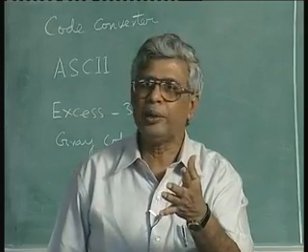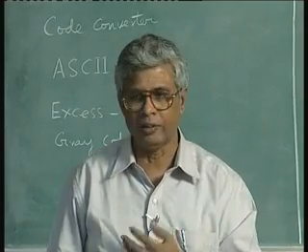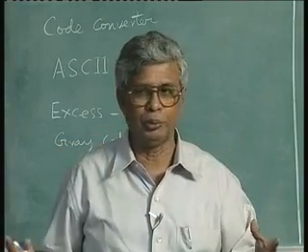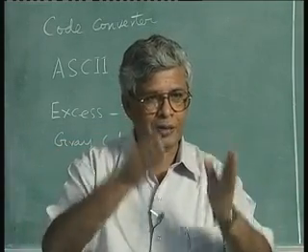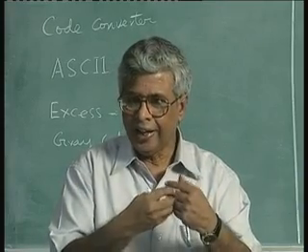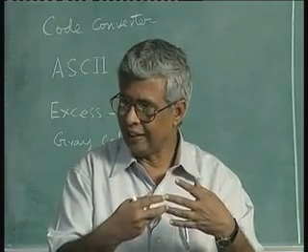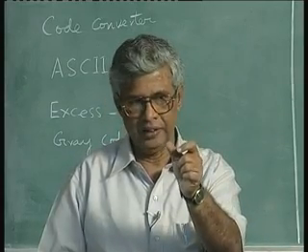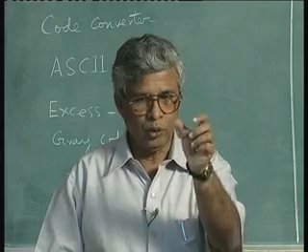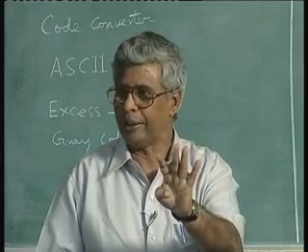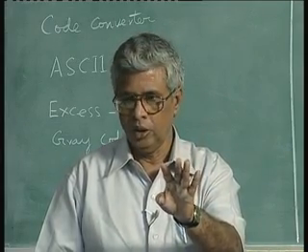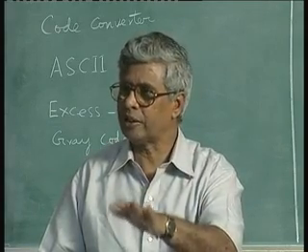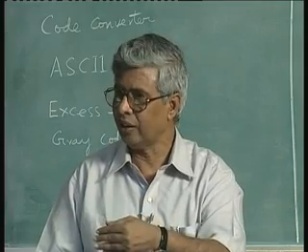There are two ways of handling decimal numbers in a computer or in a calculator. I can convert the whole number into binary and have a series of ones and zeros, mind boggling, or I can take digit by digit, convert them into binary and work on each individual digit and put them together finally. So when I consider each decimal digit as one unit, each of those units will have 4 binary bits. Out of 4 bits I can have 16 combinations, but we are only interested in 10 combinations, 0 to 9, the other 6 are not required, not used.